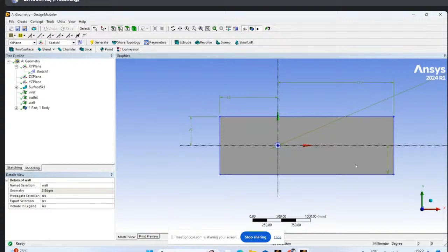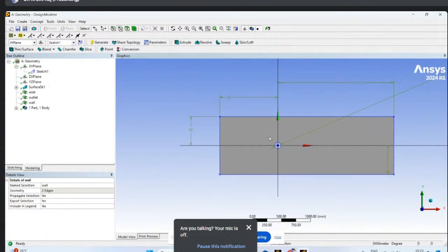We should split the things into phases, and we should give an appropriate name for each phase. So for that, suppose an O grid is there, we can easily provide that. For this type of control element it is quite difficult, but for O grid type and so on we can easily split this region, one split here, one split here, so that we will get four phases. So this line will match the mesh of the outer boundary. Here, we need to divide accordingly so that it will behave in that manner. So the mesh will be created in that manner.